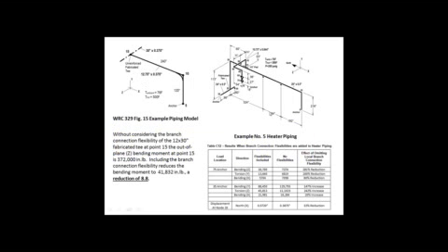If we look at the system on the right, what we see here is that we've got not a two-anchor system. System on the left, two-anchor. Very clear what's going on. System on the right, we've got multiple anchors. We've got multiple branch connections. In this case, what happened is there was a 281% reduction in moments at one branch connection and a 242% increase at another branch connection.